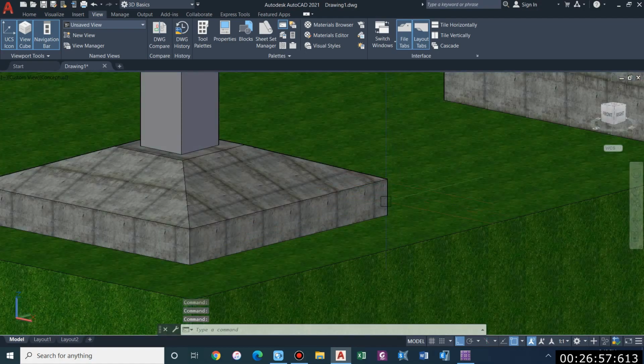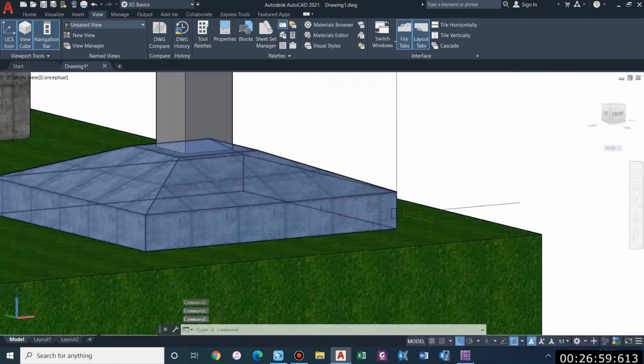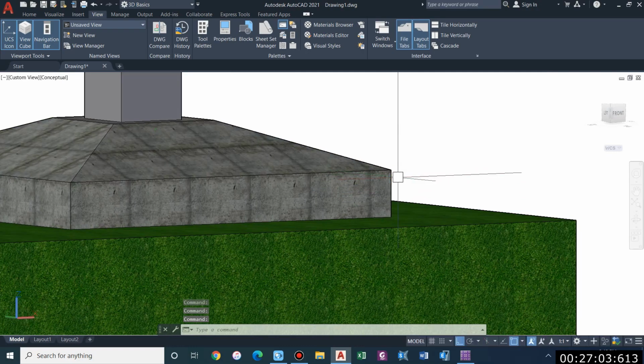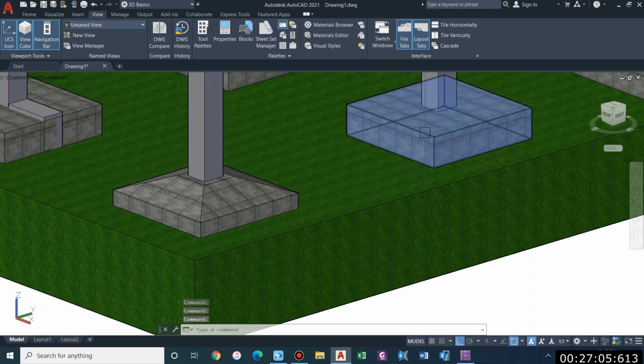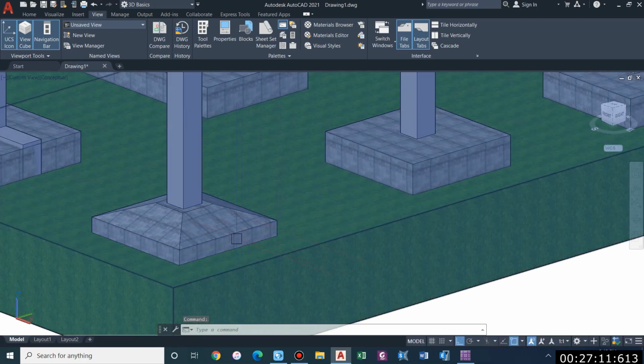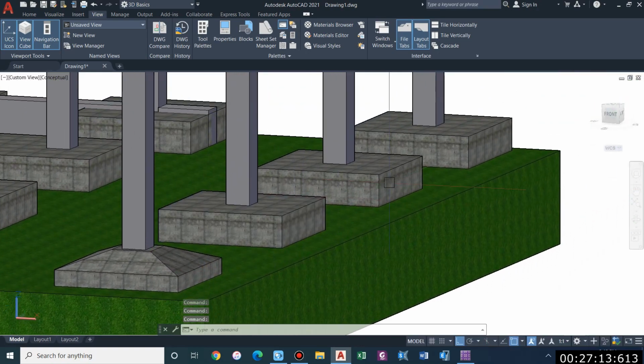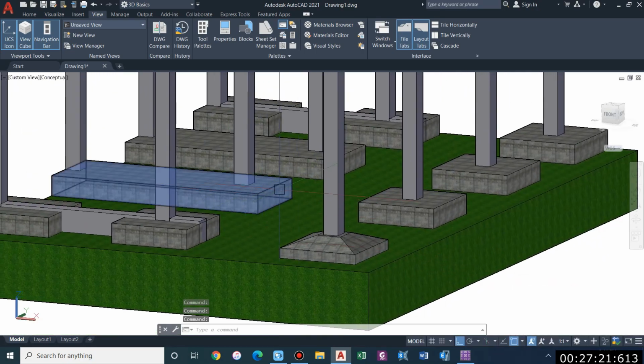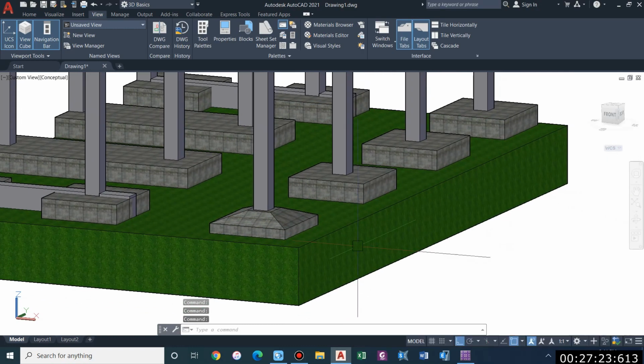And this depth, that is the depth at the edge, which is also known as edge depth, should be at least 200 mm. So we can just transform this isolated footing into this by removing the extra concrete if there is no need of top reinforcement. And generally top reinforcement is not necessary in an isolated footing, because top reinforcement is provided when there is earthquake reversal effect, but it will be necessary for a combined footing. Why it is necessary, we will discuss later on.